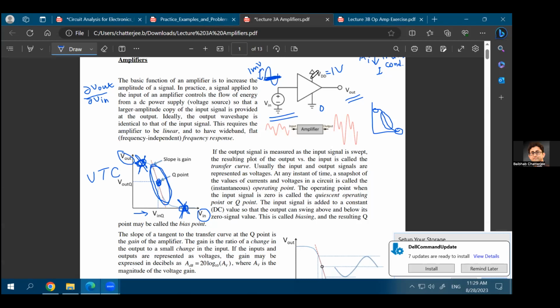near half of the VDD range. So if it has a VDD and a VSS, let's say in some amplifiers you'll have a VDD of plus 5 volt and a VSS of minus 5 volt. There the middle is near 0. Then you can have your input DC point at 0, if your VDD is plus 5 and your VSS is minus 5. Okay. So the main concept is that you have to place your input DC point near the middle of the VDD and VSS, the average of your VDD and VSS.